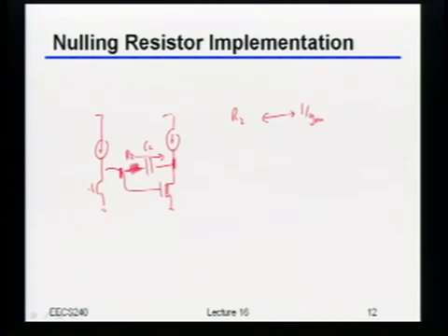Well, so what if we could take this thing and rather than allowing current to flow this way, what if we only allowed it to flow that way? In other words, we made the feedback that this Miller compensation is doing unilateral, right? So that we could only really make it feedback and there's no feed forward at all. Well, if you could do that, then indeed, the sign of the gain would always be positive. And so you wouldn't have this sort of feed-forward zero or right half-plane zero issue.